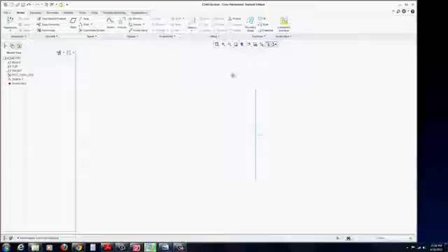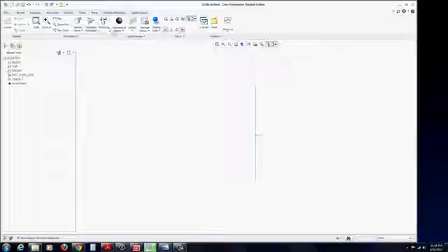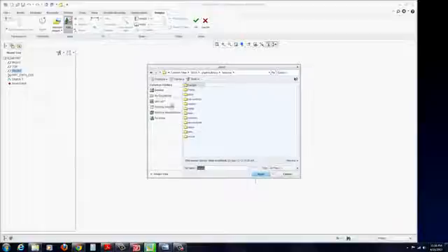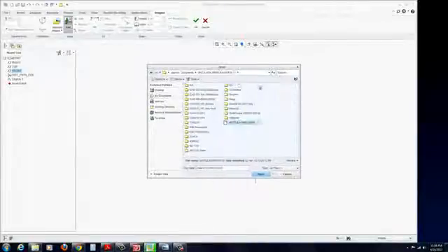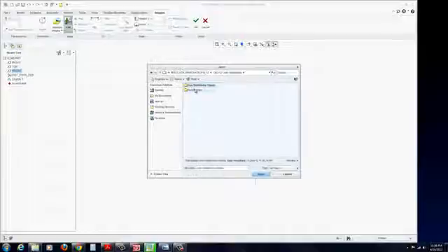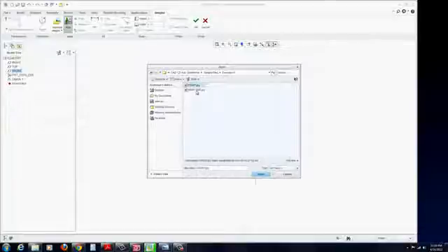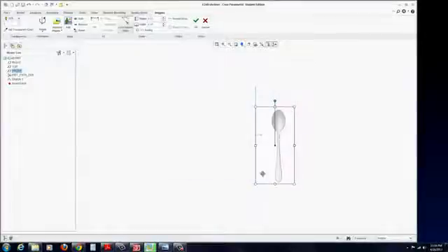Okay. And at this point, now we can drop in our images. To do this, you go to View and find the model display. And underneath there, you'll find images. I'll actually first select Add, a little cactus there, and then go select the plane you want to drop it on. And you just have to search for the images. You should have probably a front and a right side at least to work with. So I'm going to select the front, hit open.